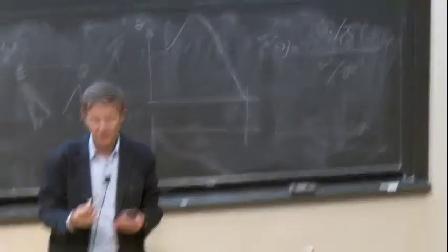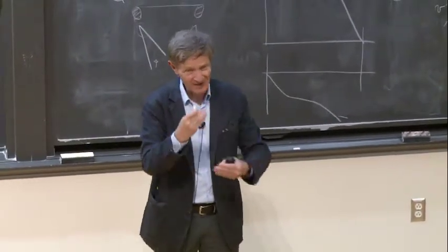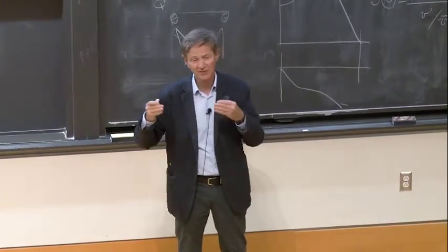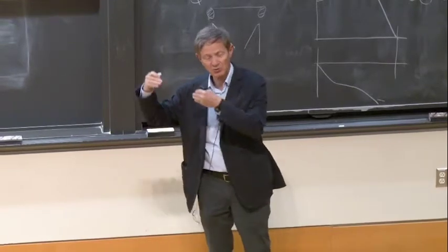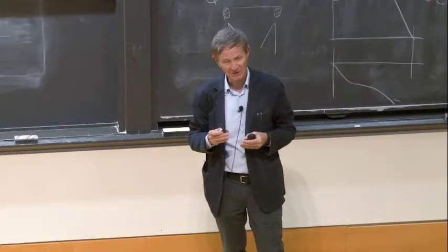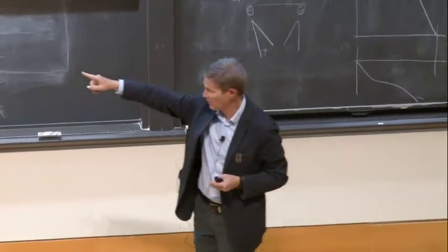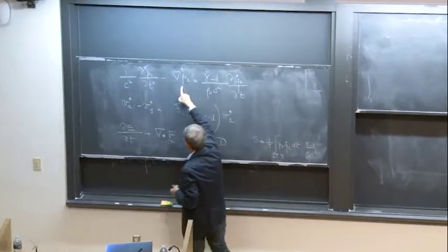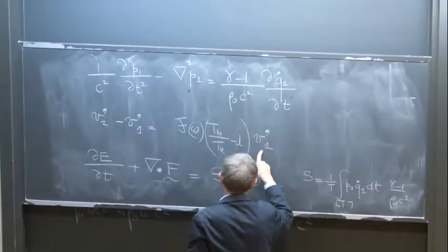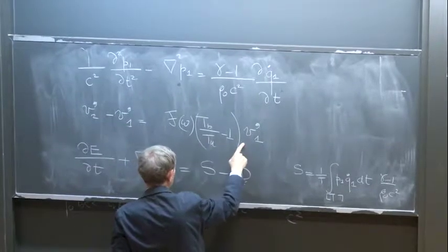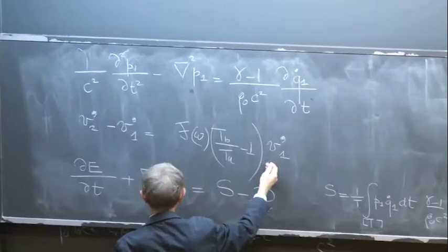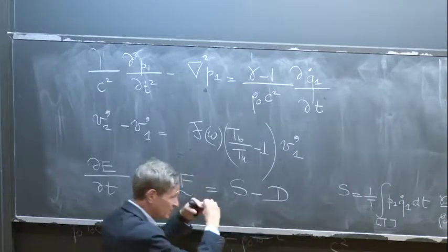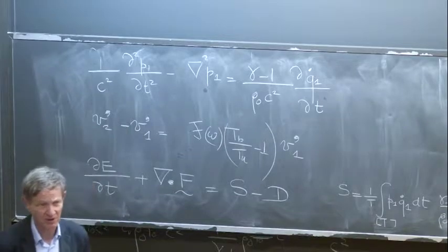So once you have the transfer function, everything else is coupled. You know, the pressure field produces a velocity field. The velocity field will perturb the flame. The flame will produce a pressure field. The pressure field is produced by the wave equation here. You see, if you know the heat release fluctuations, you get the pressure fluctuations here. This is another way of writing things. You forget about that, but you have a jump condition which is given like that. And this is more of the energy, tells you about the energy.